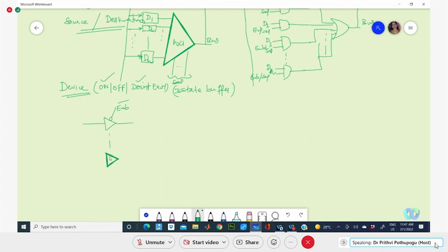So how many devices you are using, that many tri-state buffers will be taken. And each device has its own, say, data input. When you are enabling that buffer, that corresponding data will be transferred onto the bus. If we put this as, say, bus. Okay.